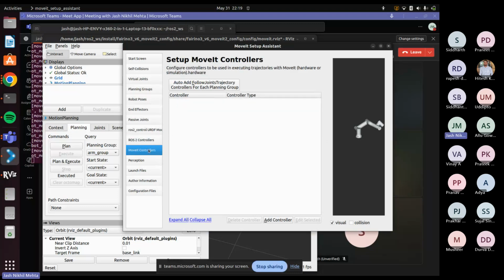Then you've got the MoveIt controller. There's a library in Python called MoveIt. For ROS Humble, which I'm using and which you all will also be using, there is MoveIt 2.0. So y'all have to study that later on. This helps you control the robotic arm using your Python code. You can extract data like coordinates from an Excel sheet into a Python code, feed those coordinates of the end effector to the ROS2 code, to the MoveIt controller.